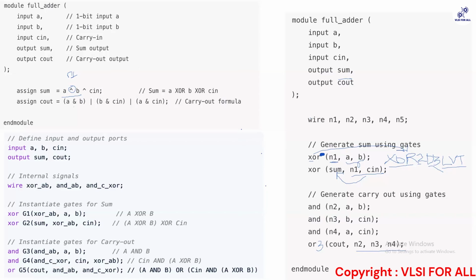It helps in reducing the congestion as well, right? Because you have a lot of resources which are empty in your core area, and there can be direct routing, no detour. So it will help in improving your timing, right? Your speed as well will increase because the tool now doesn't have to route too long. So this is the way the optimization engine works in the synthesis.